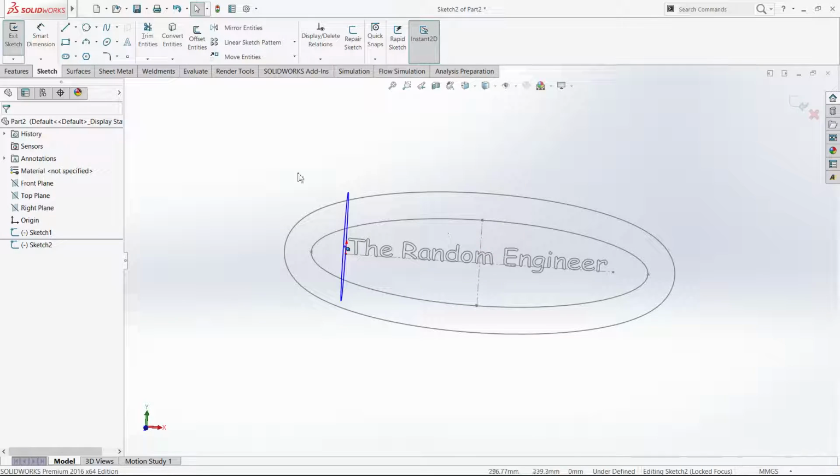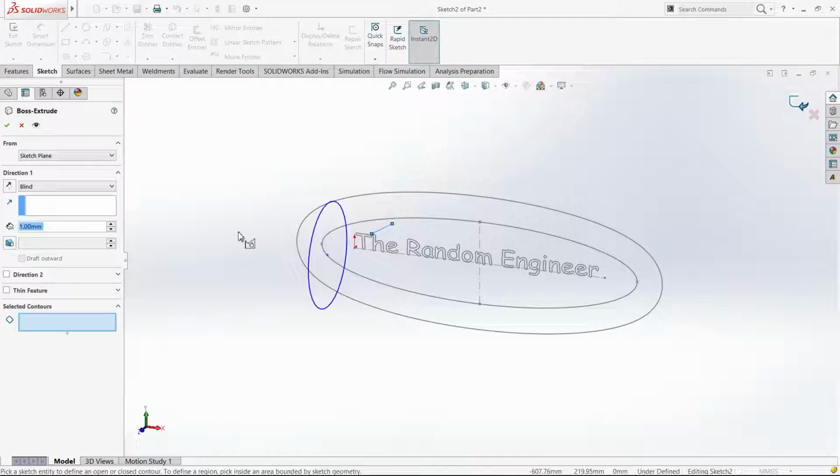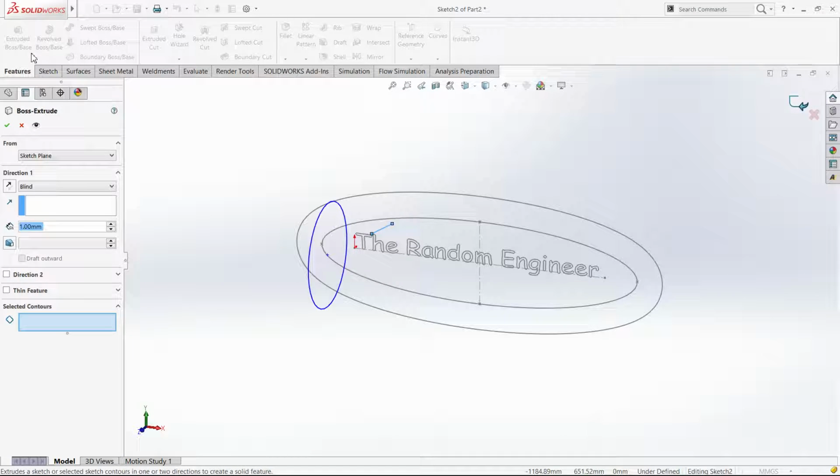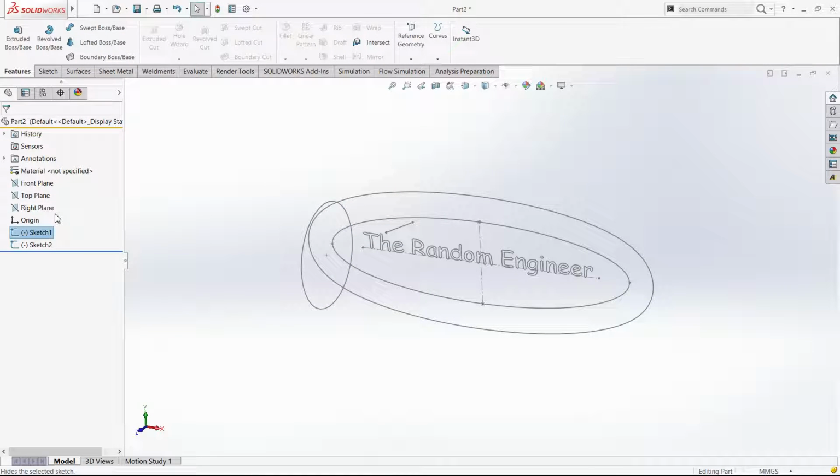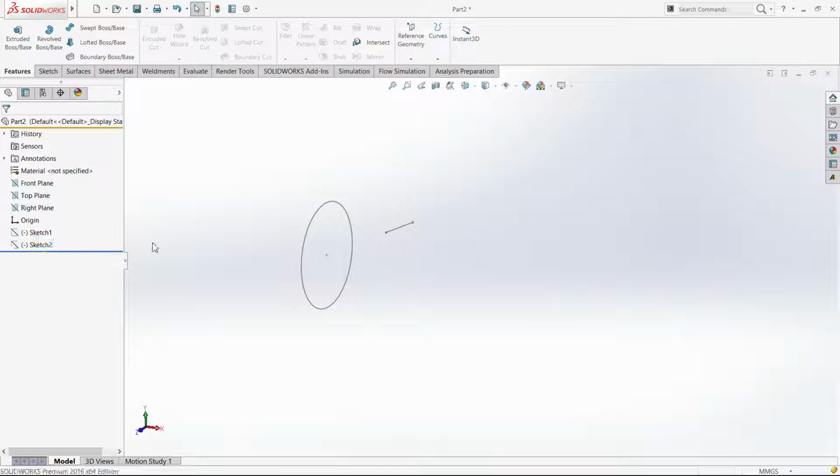And that's not what we wanted, because we already have our defined geometry. So we can exit the sketch, and since we clicked on the extruded feature, it's going to recognize that geometry that we just drew, and it's going to ask us to do something with the feature, but we don't want that, so let's just exit it, and we have two sketches now. Sketch number 1, sketch number 2. If you have maybe too many sketches, you can always click them with the left button and hide them, so you can only see what you want to see.